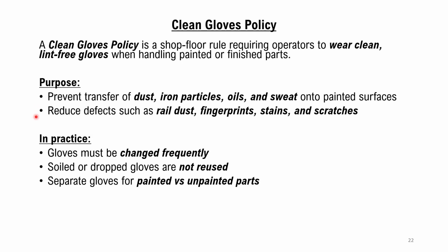Reduce defects such as rail dust, fingerprints, stains, and scratches. In practice, gloves must be changed frequently. Soiled or dropped gloves are not reused. Separate gloves for painted versus unpainted parts.